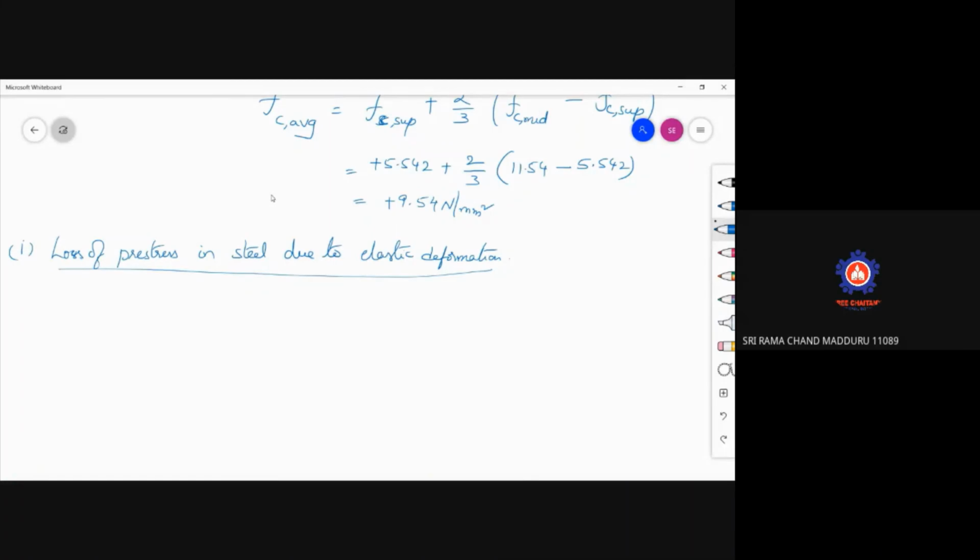It is said that 12 wires of 7 mm diameter are there, but the data is not given regarding the sequence of stretching and anchoring. If stressing and anchoring are done all at a time, then the loss due to elastic deformation is 0.